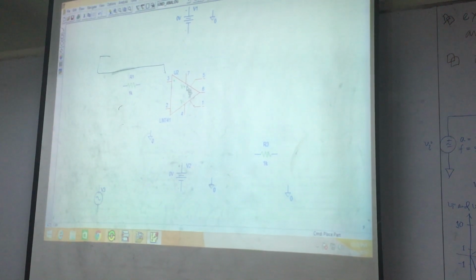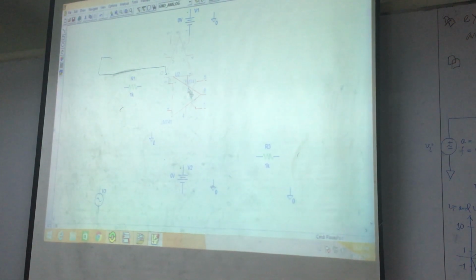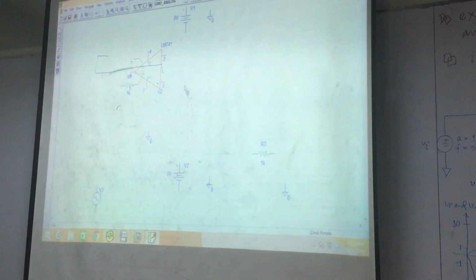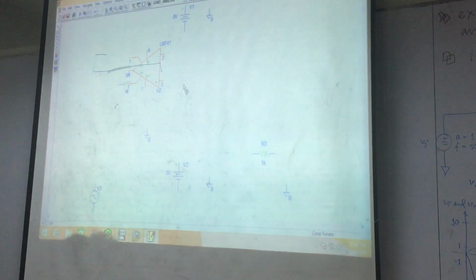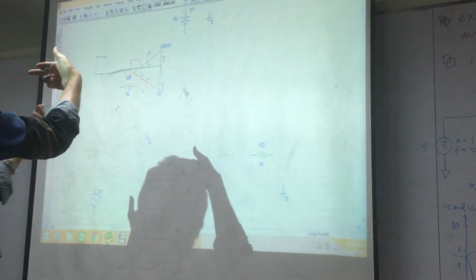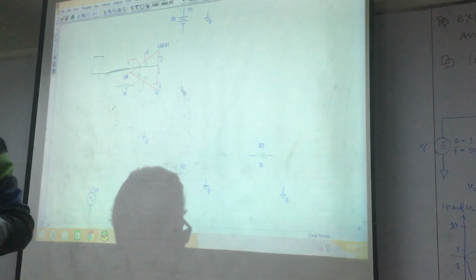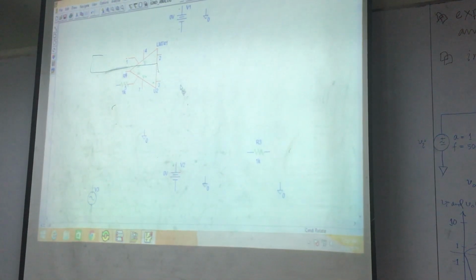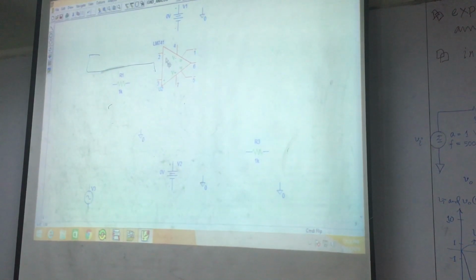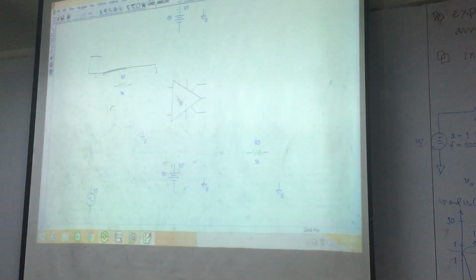I've already selected it. So, rotation, Control R twice. You see? Minus is on top. Now, plus is at the bottom. But problem, it's facing this way and that facing this way. The opposite. How to change that? Flip it. Okay, Control F. That's it, done. So let's keep this guy, let's move it here.